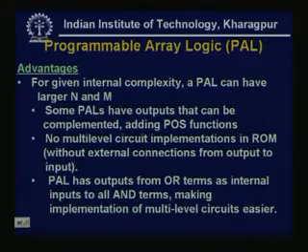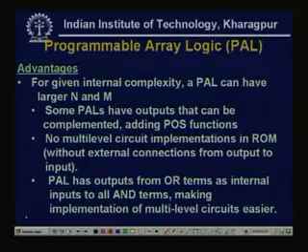As it is a fixed OR plane, in the design itself the larger value of M can be selected. Some PALs have outputs that can be complemented, adding POS functions. This is a very important property.